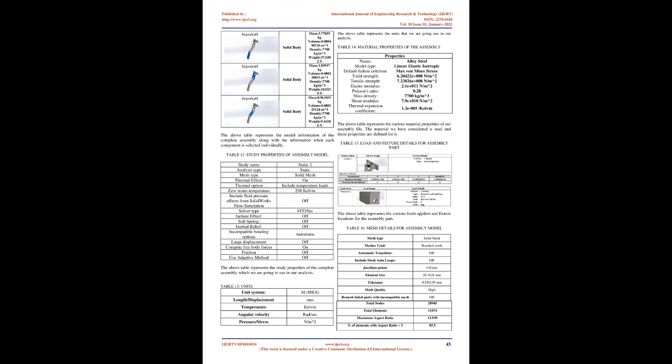9. Under type of study, on the left-hand side of the SolidWorks Motion Manager, select Motion Analysis. Speed 1000 rpm. Results: forces, motor torque, magnitude, rotary motor 3. The above plot diagram represents the initial results of torque for rotary motor 3, which is plotted against time at 1000 rpm. We observe that the frequency increases and decreases in a step pattern.